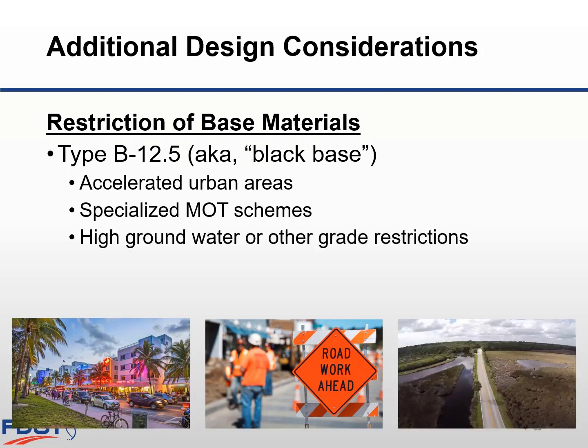High groundwater and back of sidewalk grade restrictions make it difficult to obtain adequate design high water clearance from the bottom of a thicker limerock base. The thinner asphalt base can help increase the clearance. Note that asphalt base requires a well-compacted subgrade just as limerock base. It's usually necessary to have 2 feet of clearance above groundwater to get adequate compaction in the top foot of subgrade. In areas where this cannot be obtained, the district drainage engineer should be consulted for an underdrain design or other methods.